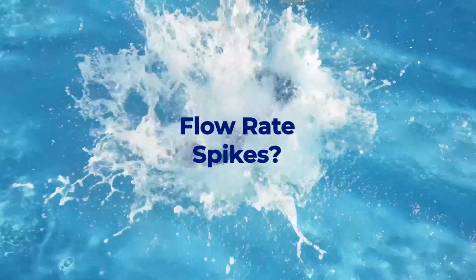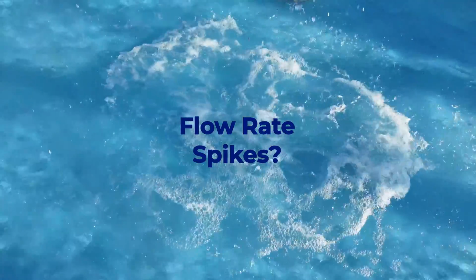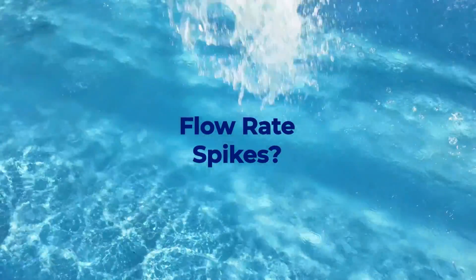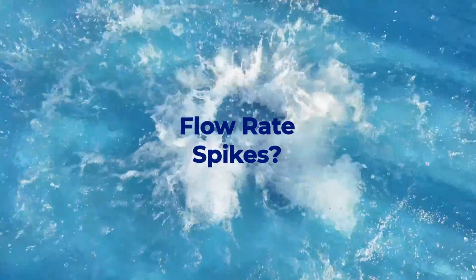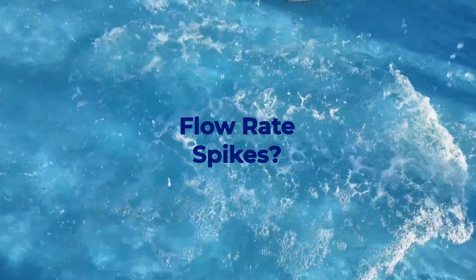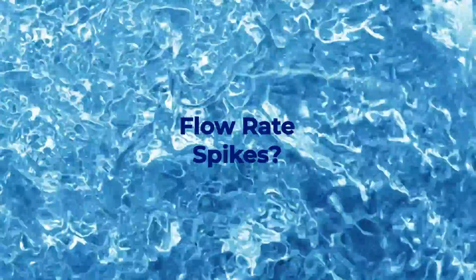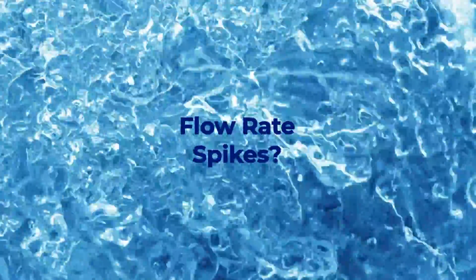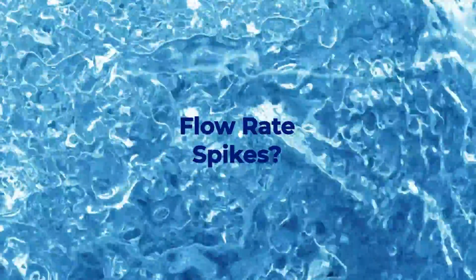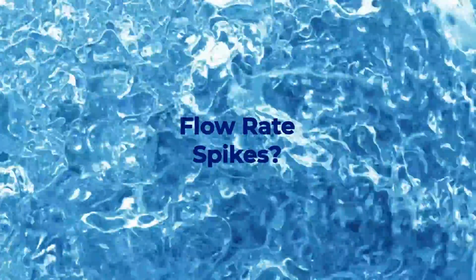If there is a significant conductivity change from a relatively low conductive fluid to a high conductive fluid, we do have the ability to detect that. If it's a non-conductive fluid, I do not see why that would be the case in a Coriolis. I'd be curious what technology you're using that's causing the problem. Yeah, that's something we may have to reach out to you, get a little bit more info, and evaluate the application and the installation.